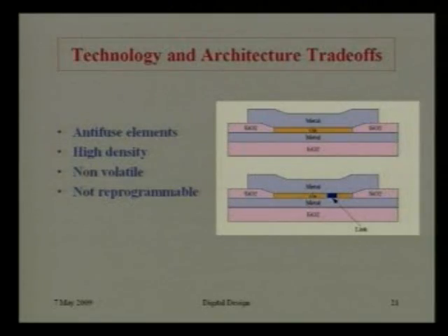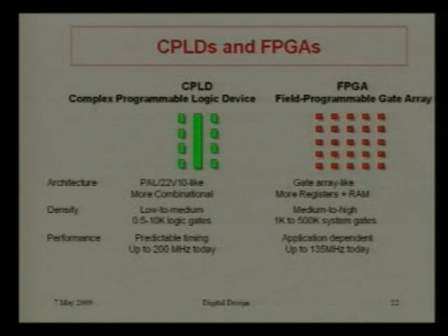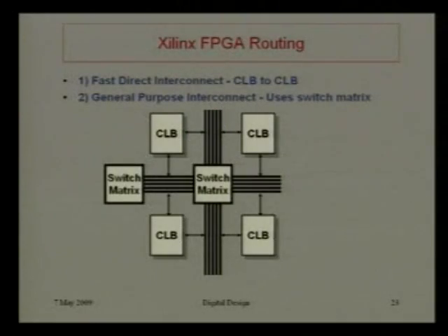Okay, I'm giving one structure. I think this is the main structure. You can get this thing. So it has a configurable logic block, the CLB, and this is actually the switch matrix, because it is programmable, which means it can switch from CLB to CLB.